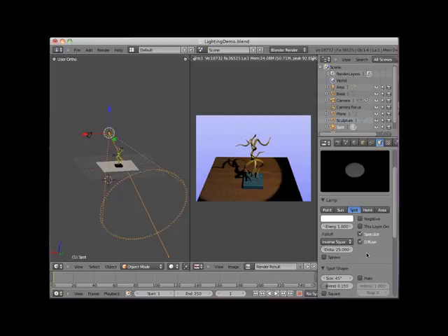Like the point and area lamp objects, the spot lamp has a fall-off, or a point in space where the lamp's energy or intensity is 1/2 of the original. Like the point lamp, the equation which determines the fall-off can be changed, as well as the fall-off distance.